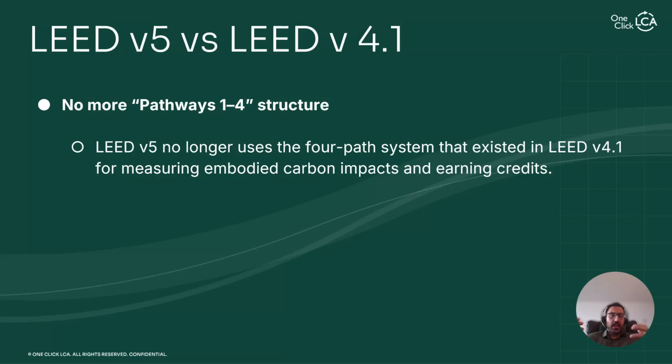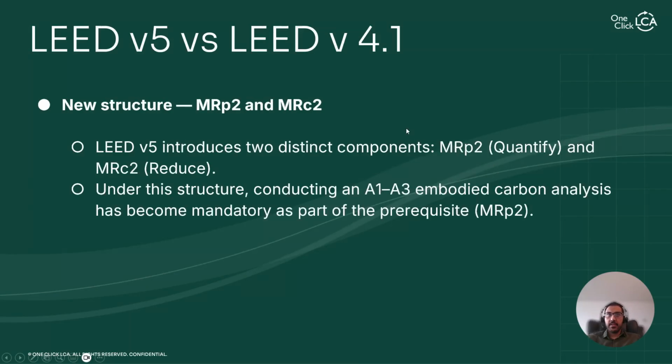But this has been changed in V5. We still do the life cycle assessment and the embodied carbon analysis, but it's going to be only one option. We have 2 other options as well to achieve the credits. And in LEED V5, probably the biggest change that we're going to see is the fact that we have to do the LCA, and it's mandatory as a prerequisite.